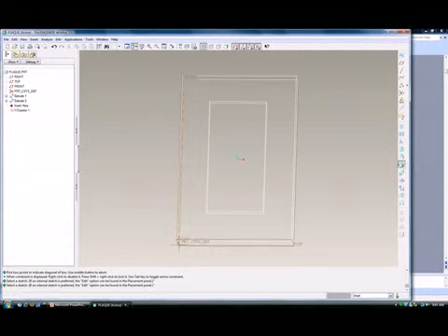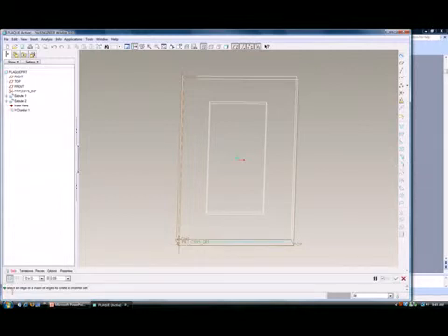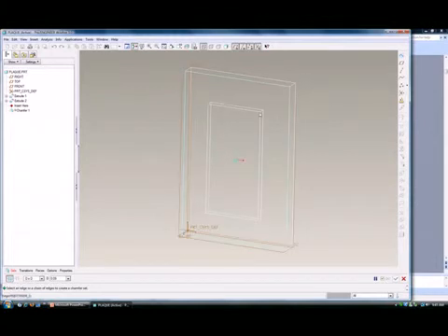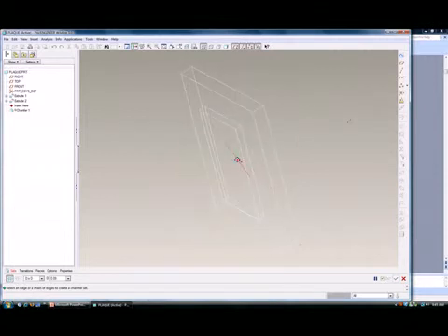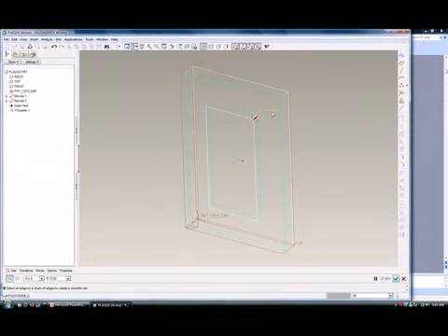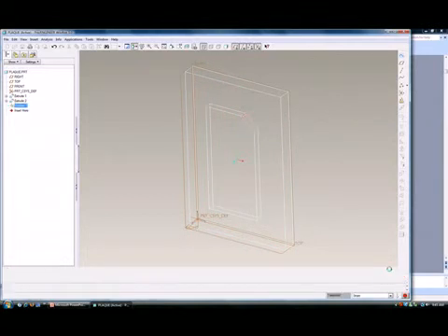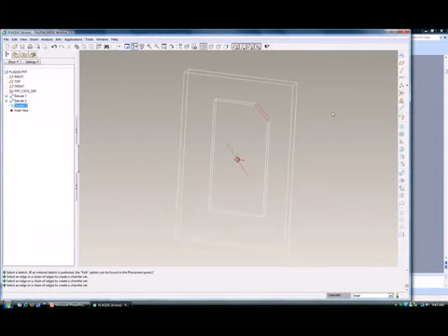Click on chamfer, and then Pro is calling to select an edge. So what I'll do is I'll select this edge here, this small little edge here. Select it. Okay, and I believe the dimension is actually 0.5. Hit OK to confirm.